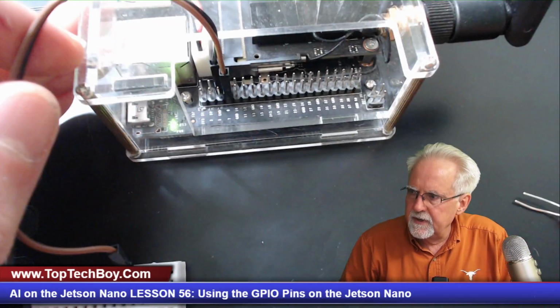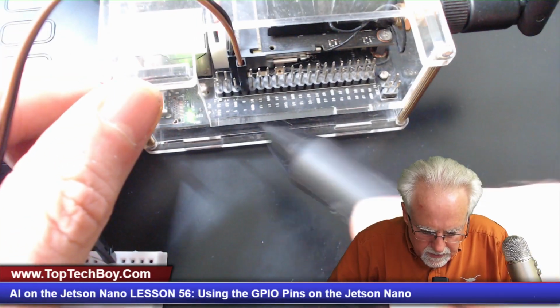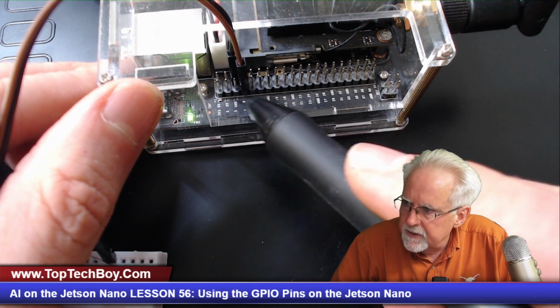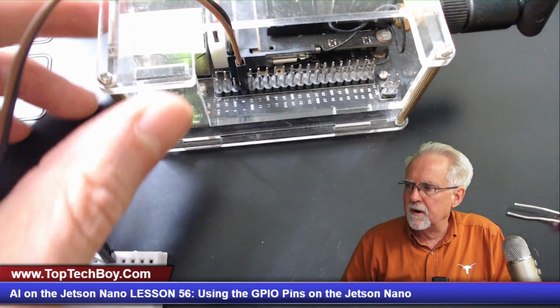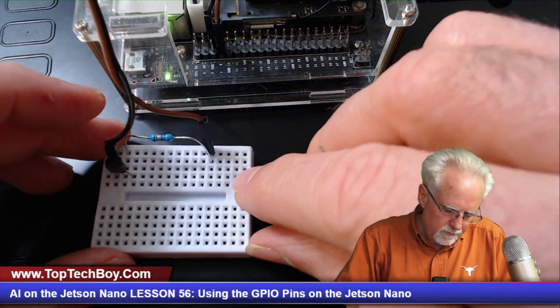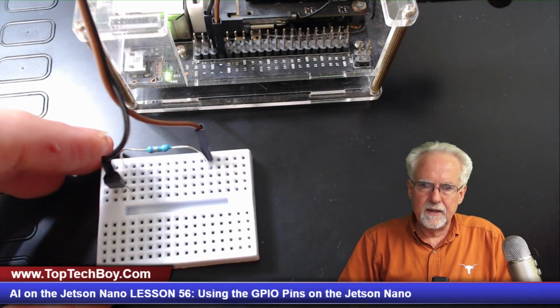Now there's a couple of things. Pin 7 is on the outside, and remember it's pins 1, 3, 5, 7, because the outside pins are the odd ones. And so now I have my control pin hooked up. So now we just need to put in the LED.